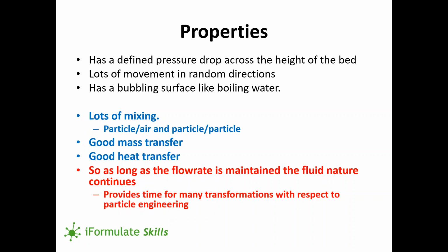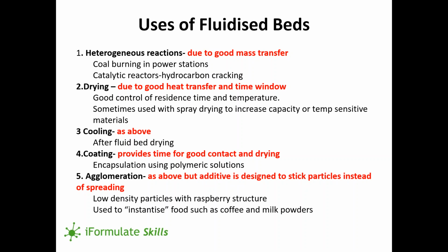So the point here, though, around time is that you can have very long residence times in your bed because it's maintained by the gas flow rate rather than the height of a tower with respect to gravity. So it gives you opportunities of drying at much lower temperatures over longer periods of time. So on the next slide, we can see how those properties drive the use of fluidized beds.